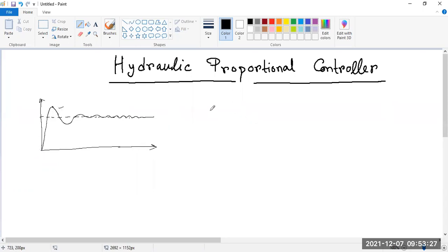You can see in your induction motor, the first time it will take some high ampere. Okay, maybe it is 5 to 10 ampere, and then after that it will come to the steady state, drawing only 1 to 2 ampere, as per the rating. So whenever it starts, it will directly go to 5, and then it will come to 1 or 2 ampere. Okay, so this portion is also the nature of a machine.